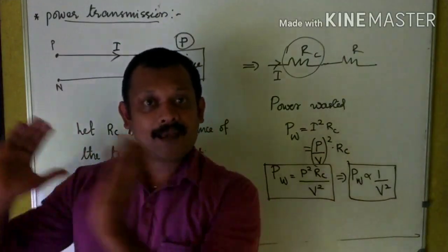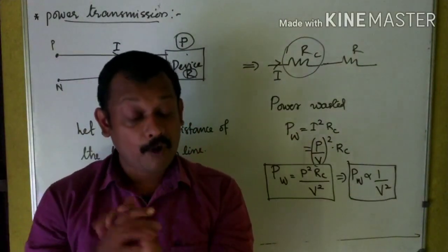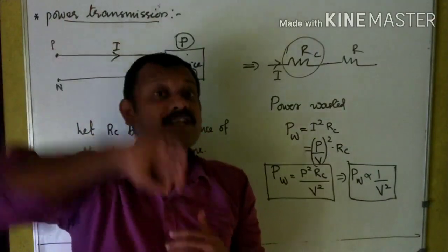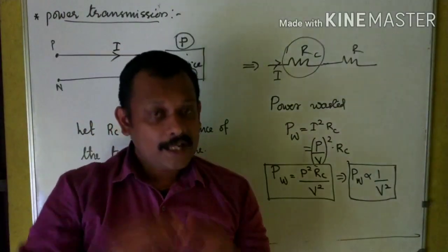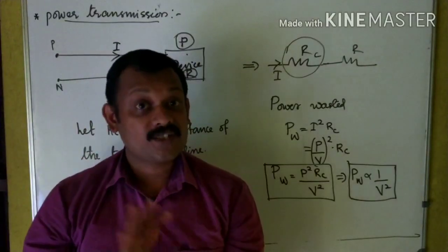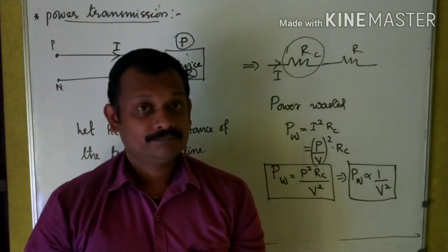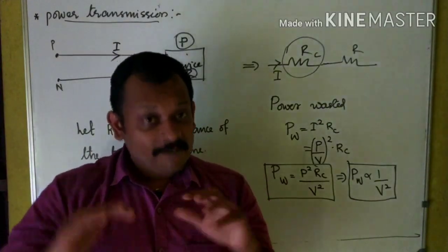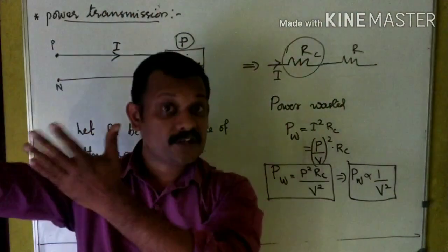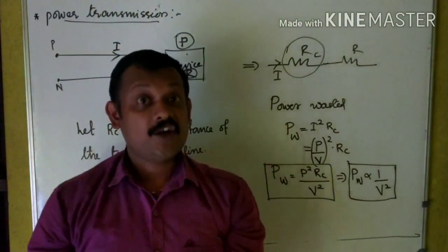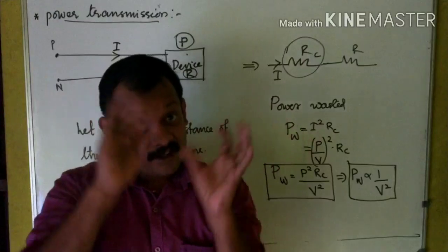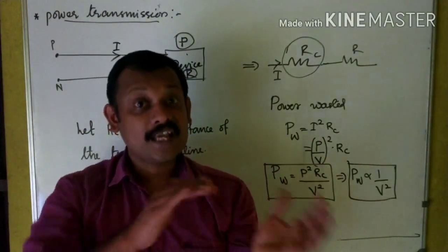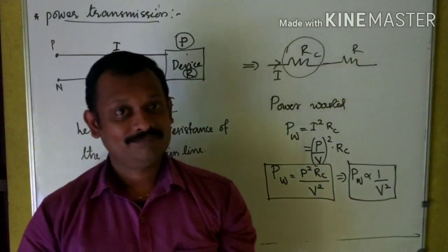Let us say from a 66 kilovolt power station, the signal is transmitted at 66 kilovolt. Then using a step down transformer, it is converted into 11 kilovolt, that is to local substations. From local substations, the transmission line near us will have 11 kilovolt to supply, which will further reduce by another step down transformer to 230 volt, and the same is what is transmitted to our home.